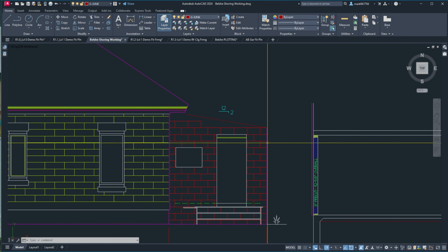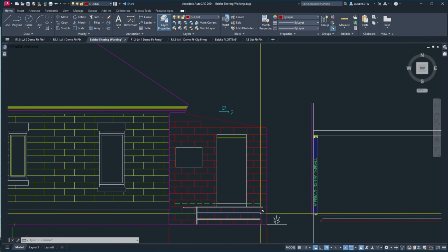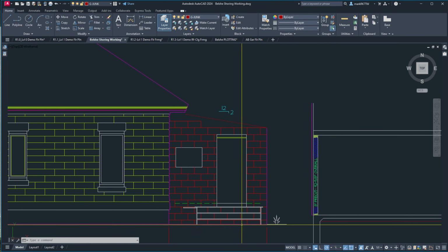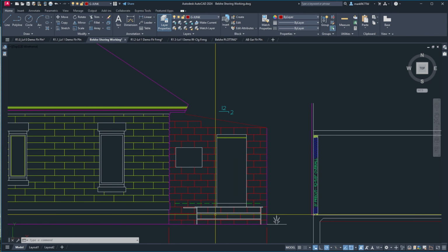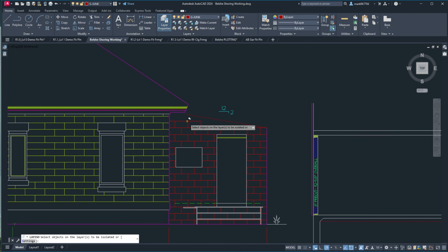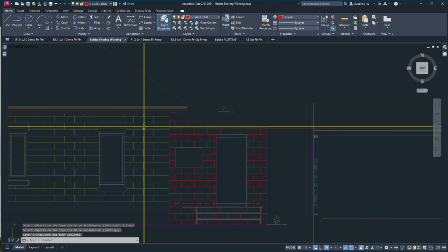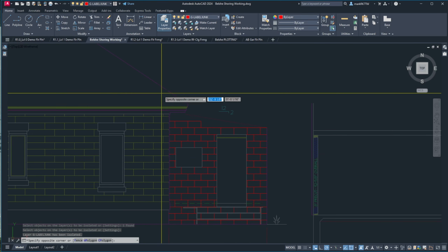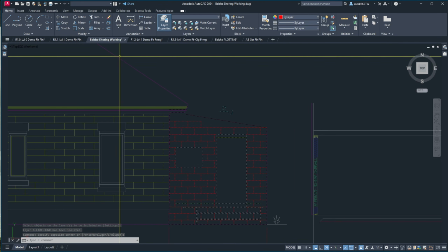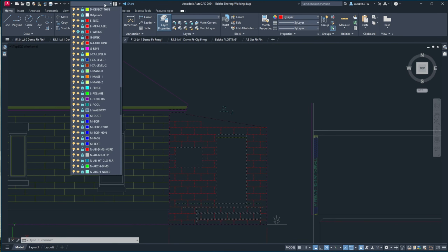So if I want to change all these, look at all of them, and they're stuck inside here behind this stair that you can see through. This is a house fire issue, so I'm going to be keeping the wall, but I'm doing the as-builts right now, and so I want to change those to this layer. So I'm going to isolate them by picking that layer, entering it, and boom, you can see the others are grayed out. So now when I select them, it looks like it selected the other layers, but it's going to give me a message that says, hey, sorry, couldn't change those because they were locked.